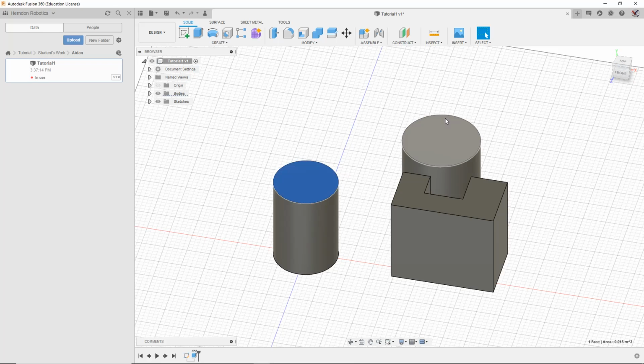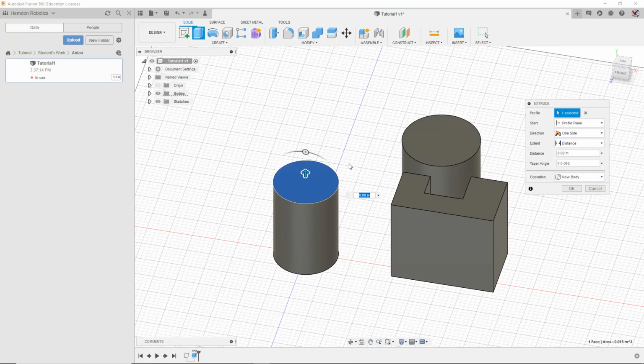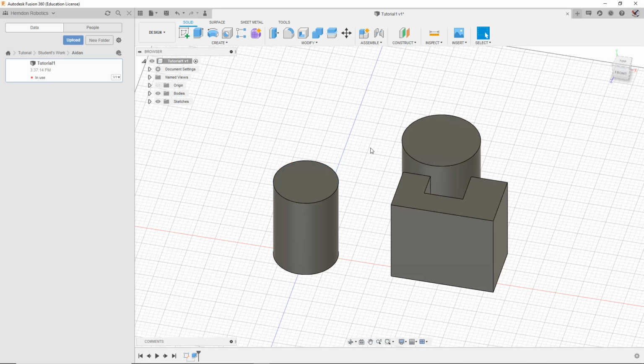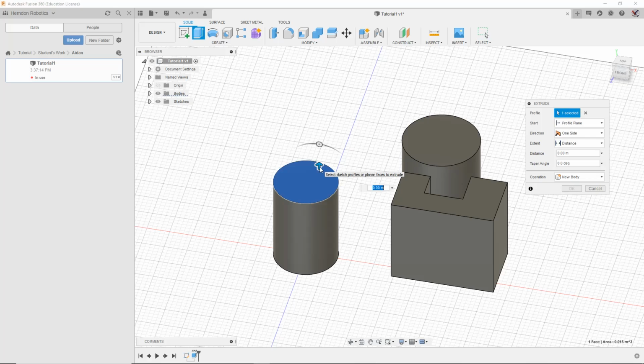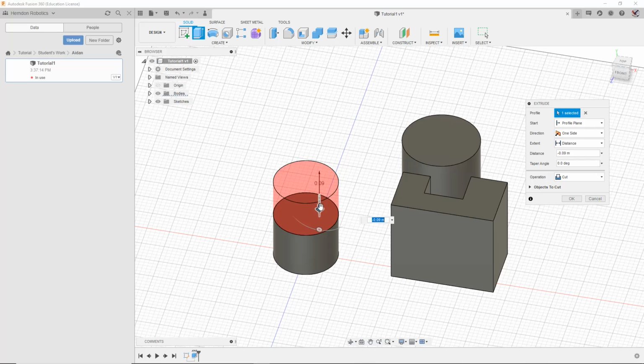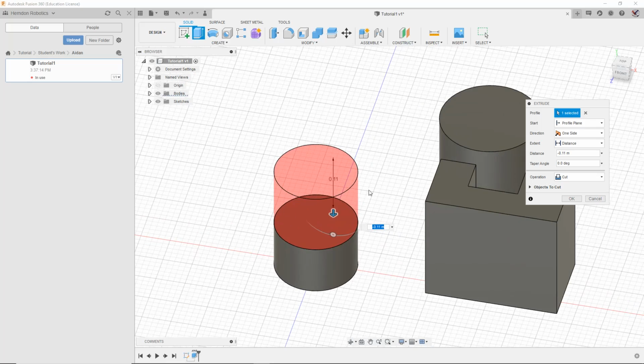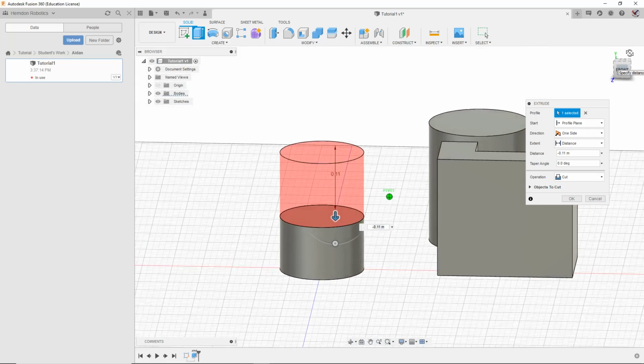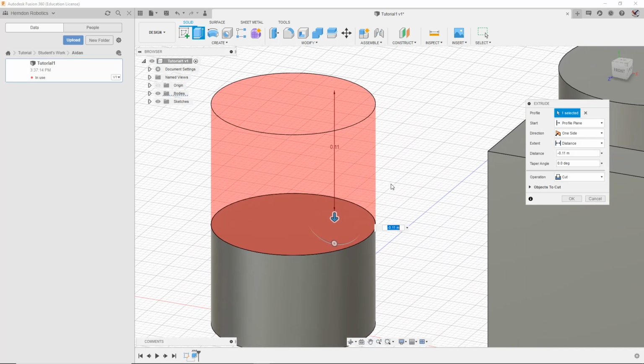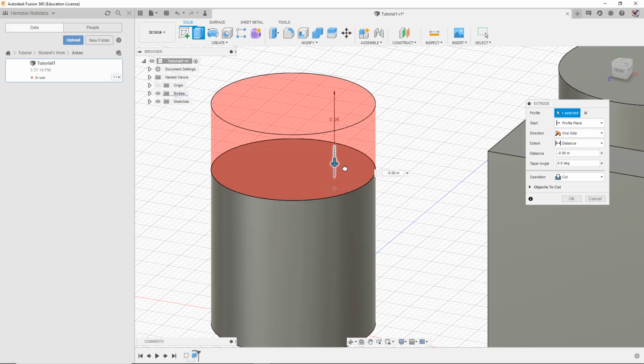And let's say you could just select them individually now and say, I want to make this one a bit taller. I can select this face. We don't need to sketch it anymore because we have it. So by left clicking and then hitting E to extrude, we have this arrow. We could pull it up, or we could pull it down. When we pull it up, it just looks like a normal shape. Pulling it down makes it kind of red and invisible and gives us this little shadow, like so. And then with this, what we can do is lower it down by how much we need.